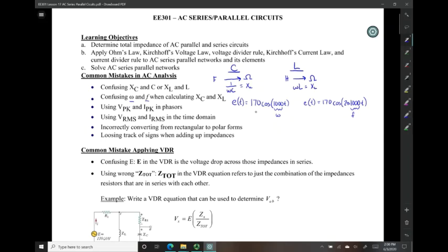And how you do that is you grab the peak values, this is a voltage peak, and voltage RMS is simply equal to voltage peak divided by root 2. Similarly, current RMS values are peak current divided by root 2. And you can just rearrange that to solve for your voltage peak if you need to go back to the time domain.